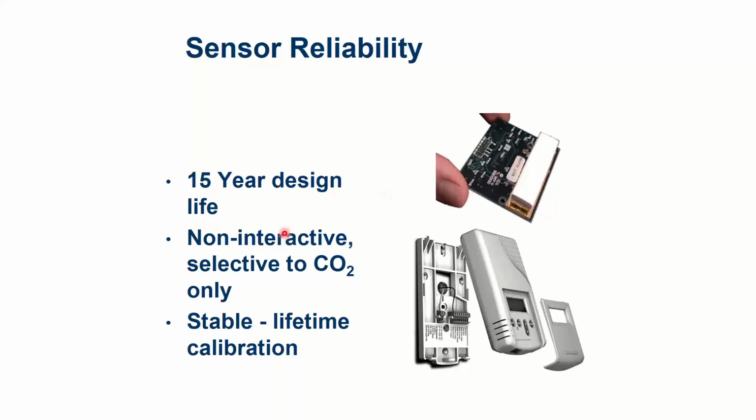If you have a 10-year warranty and the sensor goes out of calibration on year 7, most of them are no longer calibratable. We used to have a button on a lot of them. You take the cover off. You could flow gas through there with a tube from a tank, and then press the 0 out button to kind of wipe it out. So we'd flow nitrogen through there, press the 0 button, 0 it out, basically recalibrate it to nothing,